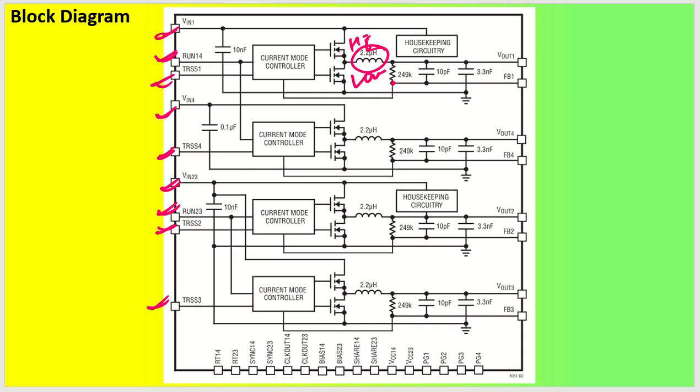As you can see, this will be generally the feedback without micro module devices, so this will be considered as R1 and outside it will be R2, like that we will be seeing. This is very simple to view. You can see inductor, R1, R2, which have to be designed outside. Generally in all the switching regulators that we have already seen, we were required to design the value of inductor and the complete value of feedback resistor voltage dividers to set the output voltage.